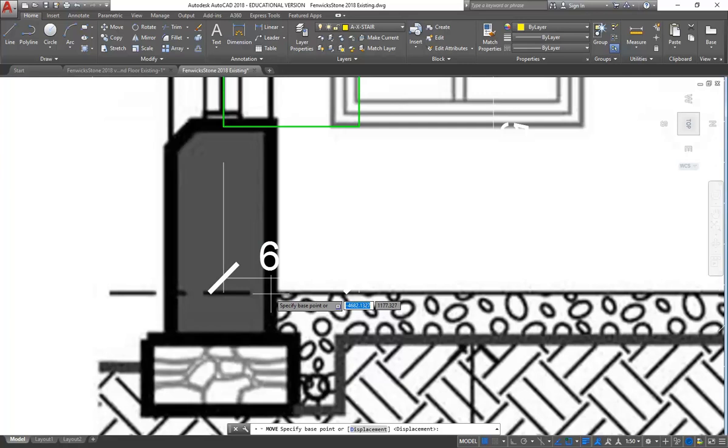And I don't know, have you ever been told something different when you're taught by people who draw by hand? Have you ever been told that the line weight should go inside what you're drawing? Anyhow, you'll find a lot of older architects will still draw that way. So you won't always see it. See how here the line weights stick out? And that tells us that the lines are centred, or the line weight is centred over what's been drawn. But you need to be aware that in many cases, especially with older drawings, that won't be the case. In this case though, we know this has been drawn in AutoCAD, so the line weight is centred.